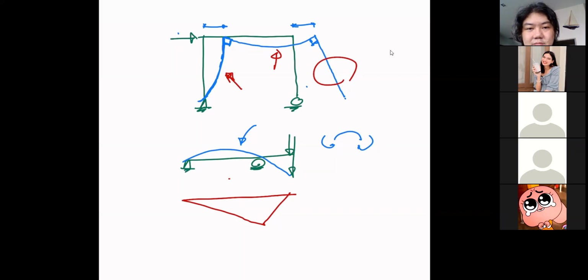Is it necessary to write a sign convention for the shear force diagram or bending moment diagram, like writing that the smiling face is positive? No need. It's a bit tricky with the shear force diagram, but for the bending moment diagram, you should draw it on the correct side of your member.